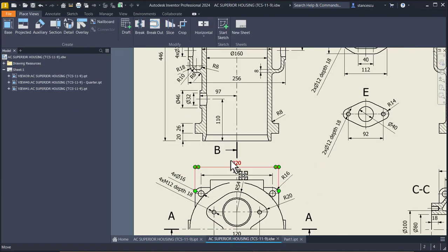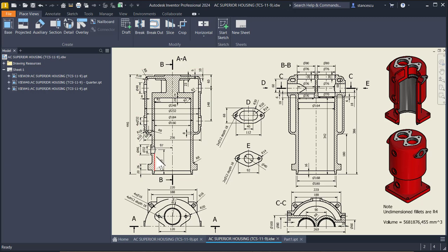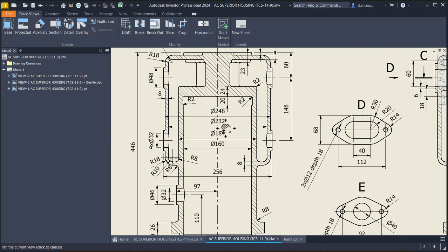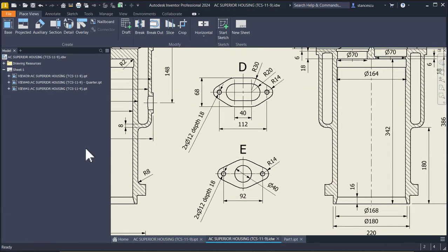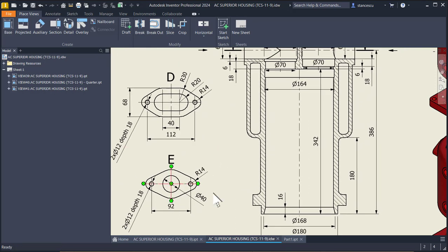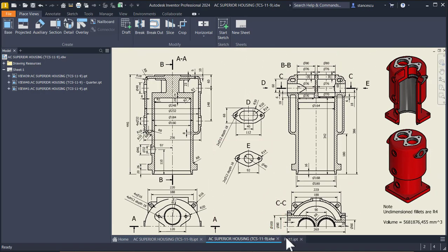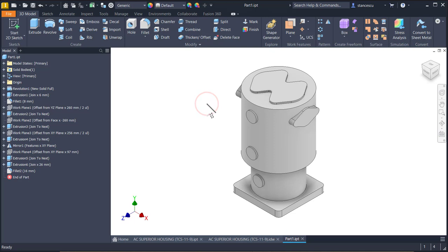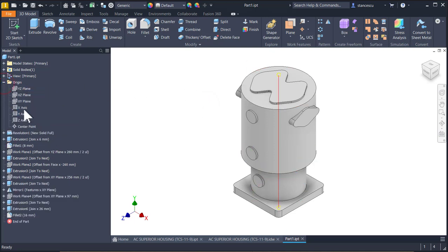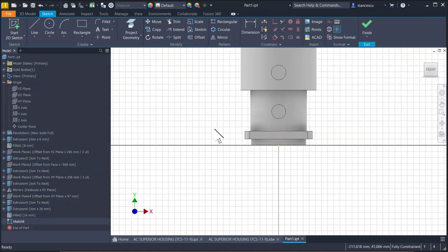Now we go to the internal volumes. You see, this one is a major volume, and also this. They have the same axis, so we use dimensions from here to apply for creating this close contour. Dimensions are here, and we start. The plane is XY for a new sketch.